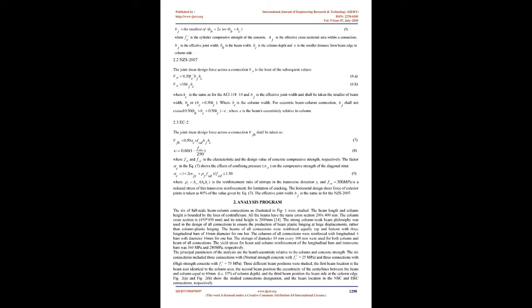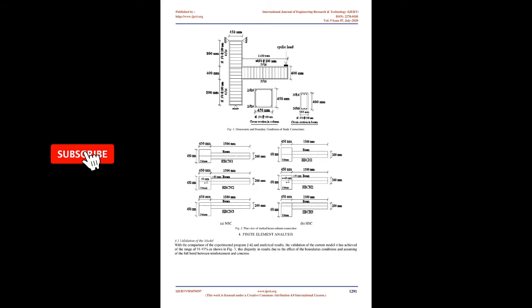Most studies are devoted to the seismic behavior of reinforced concrete beam column joints constructed from NSC with compressive strength less than 40 MPa. With widespread use of HSC with compressive strength approaching 140 MPa, studying the seismic behavior of HSC eccentric beam column connections has become necessary. Present design guidelines are also focused on limited experimental work on eccentric connections and take into account post-earthquake observations of increased damage to external connections between the beam and the column center lines.